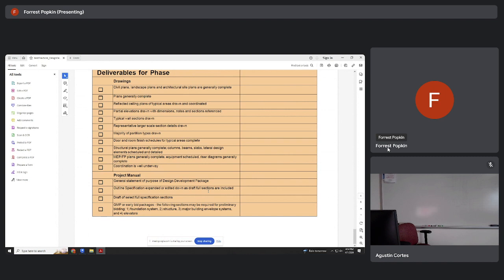So some of the beams are going to be, for example, let me show you one that bothers me. The bathrooms here, that's not going to work. These are not going to work either. You can't have an elevator with the beam. Why don't you just move that whole column line into the wall? Why don't you just move this all the way here? Yeah.